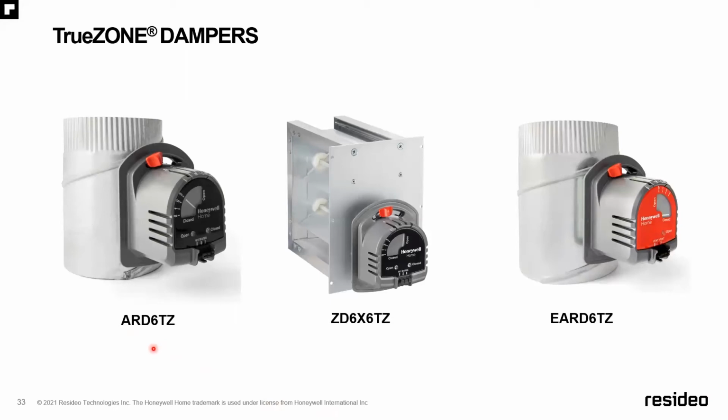Round dampers are very popular here in the South, so it's the one that I'm most familiar with. The ZD damper here, both of these are spring open, drive closed. So you only need 2 wires. It's non-polarized. So it makes it nice and simple as far as connecting the low voltage wiring.